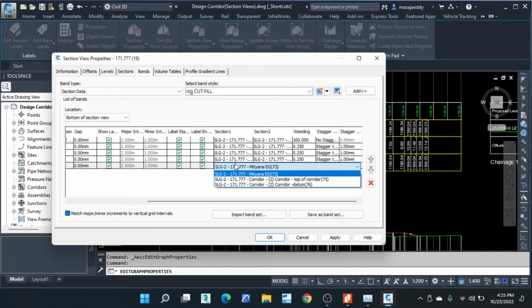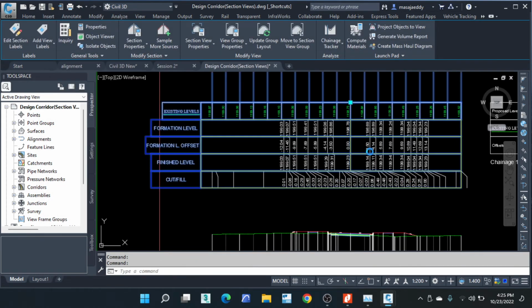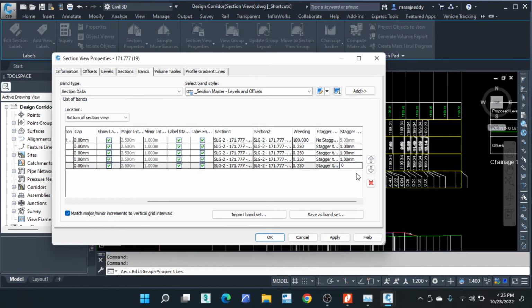So when we are cutting and filling, what are you subtracting from there? When you are cutting from the existing ground to the formation level, you are going to type in the existing ground, then you look for the formation level, which is the datum. Then click OK. So then you are going to reduce. Let's come back for a bit of orientation. So I'm going to reduce this to 0, sorry, can't reduce this to 0, to 1. Stack that to the right, everything looks fine. Click OK.